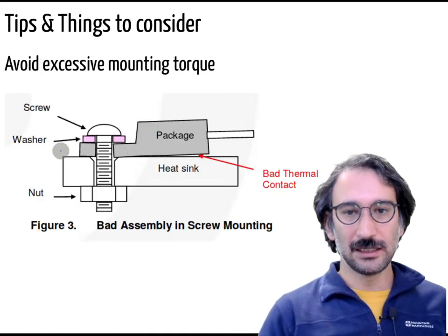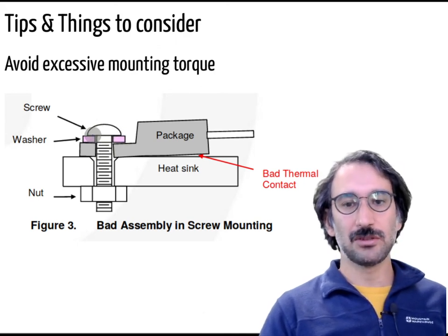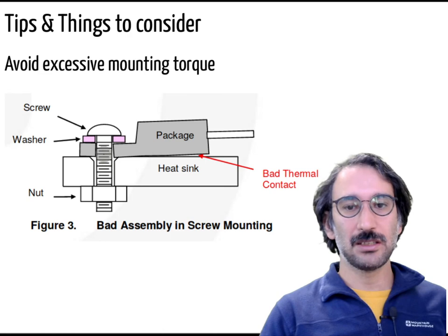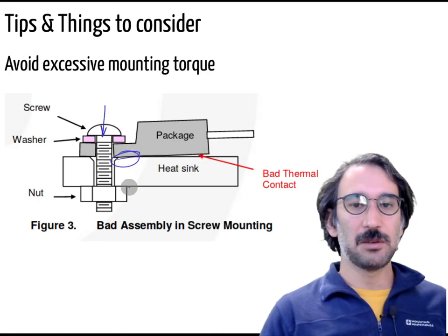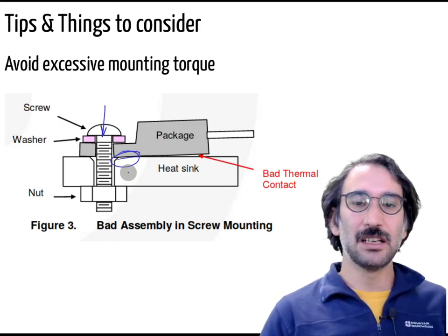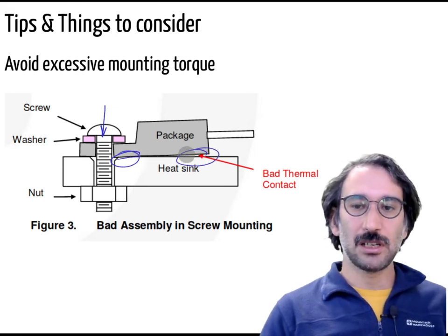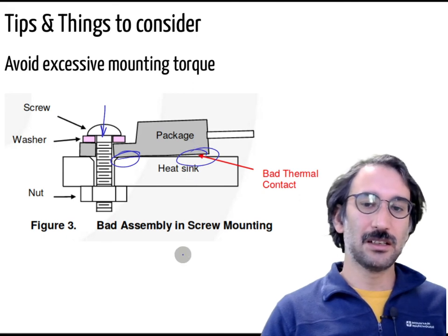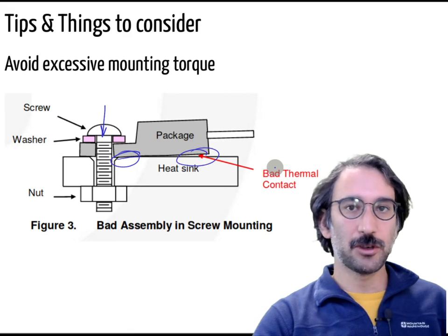And another thing can be the mechanical strength. In the data sheets you can find figures on how to mount those packages. If you have screws like in this packaging, and if you apply too much pressure, the package will be tilted in that direction. Even if you apply too much pressure, you can crack the material, you can damage it mechanically. But even if it is not mechanically damaged, you can create some gaps here, and you can reduce the conduction area, and you have bad thermal performance.